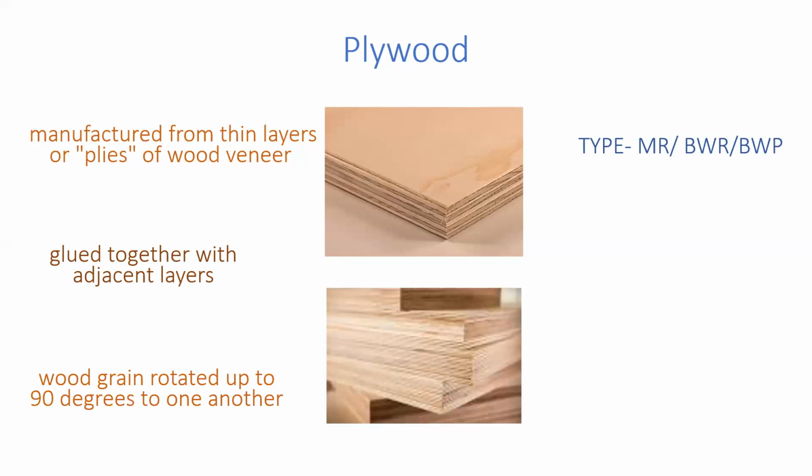That is IS 710. Also, it is called marine ply. But marine is one more grade, an upper grade ply, used for aircraft and only for shipbuilding. Usually, we get marine ply in shipbuilding factories only.